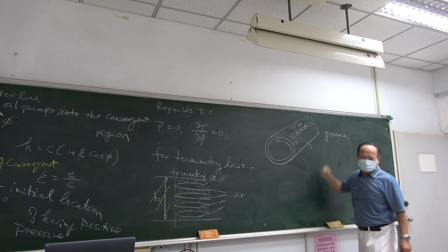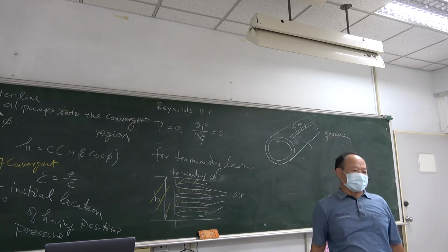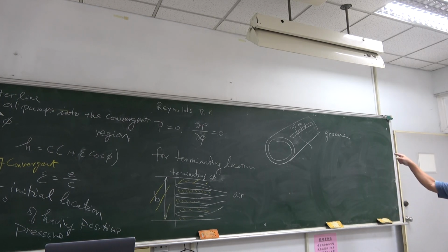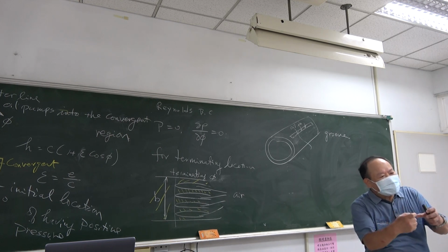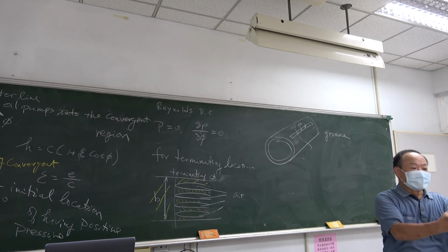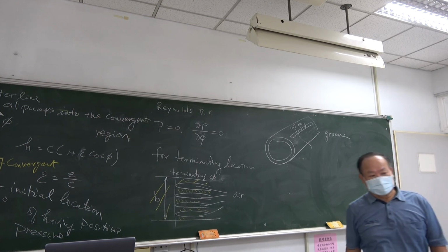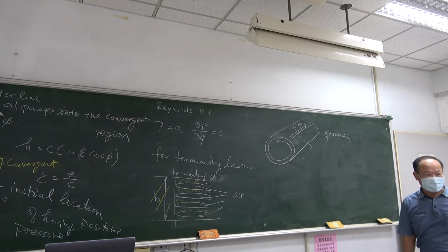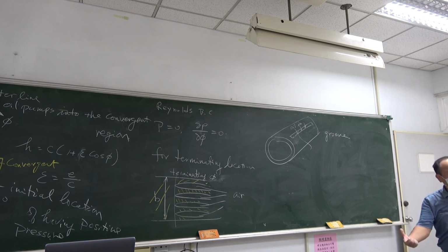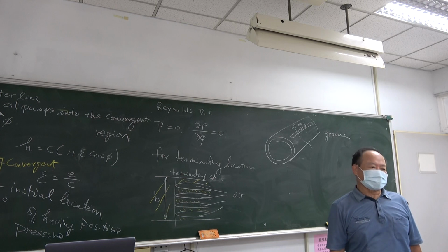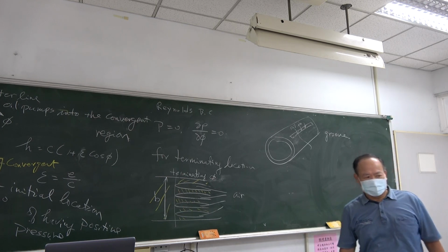The position of this groove (槽) is very important. You cannot choose the position of your hole or groove in an arbitrary way. If you have the wrong design, even if you put a lot of lubricant in, you'll find no lubrication behavior.